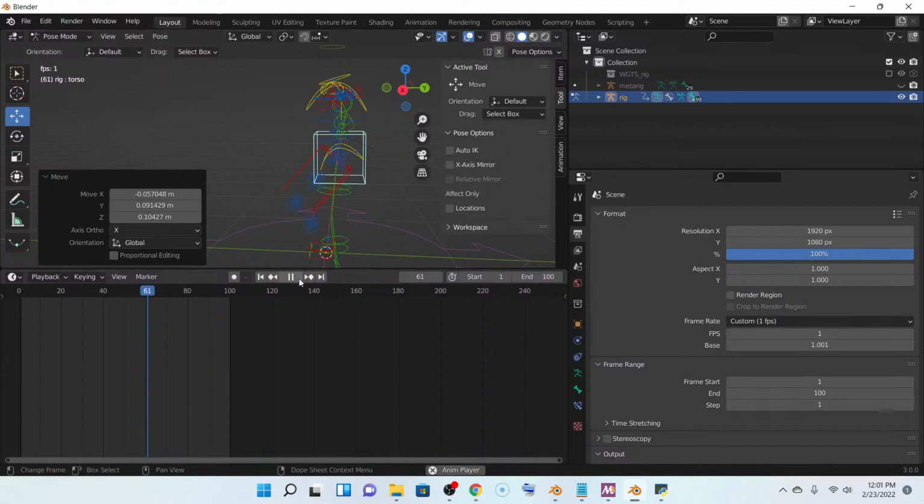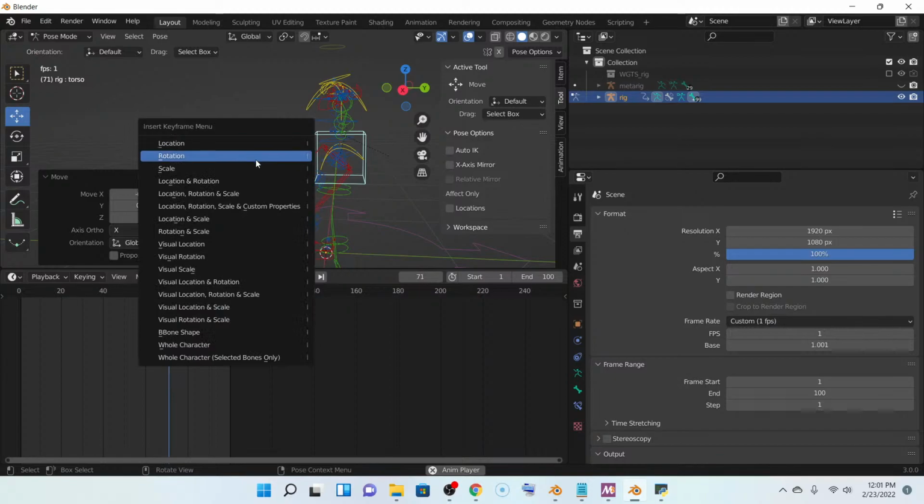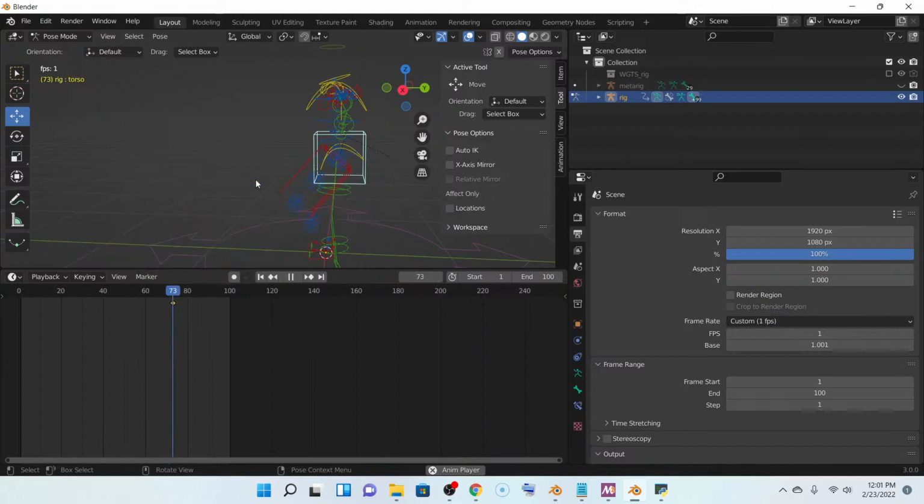So what you do, like I said, you hit that play and you start to move stuff. But you're not going to get the keyframes in there until you hit the I key on the keyboard and then create an actual keyframe at that point. And you see the keyframe was created. You can do it that way by hitting the I key, or you can use the automatic keyframe button. Either way, you can do some amazing stuff if you slow down the frame rate.